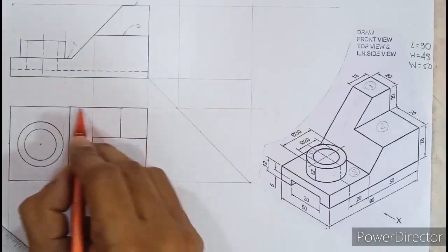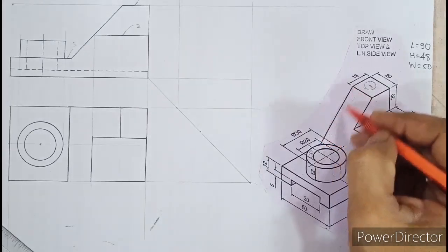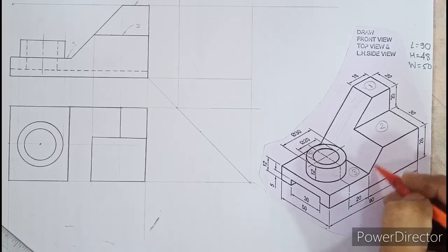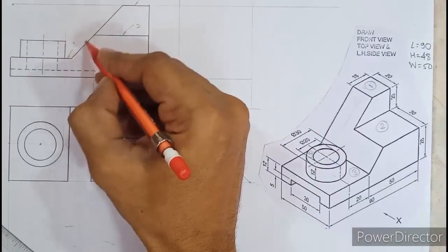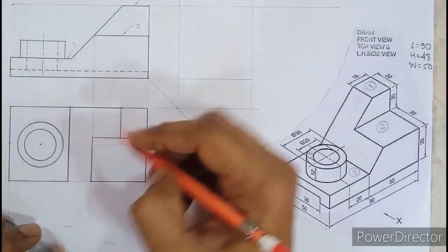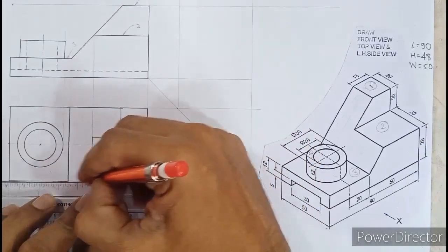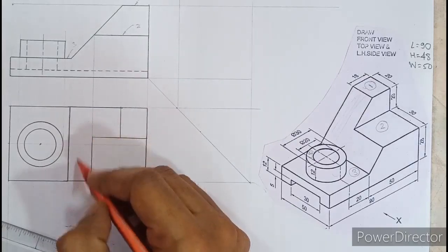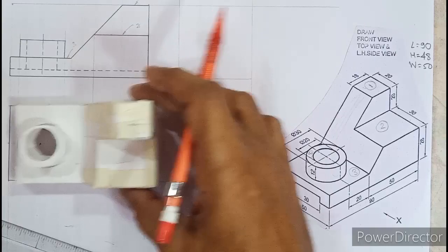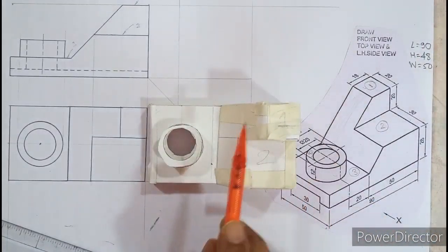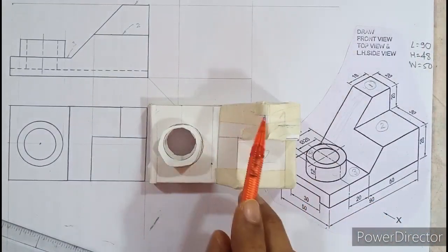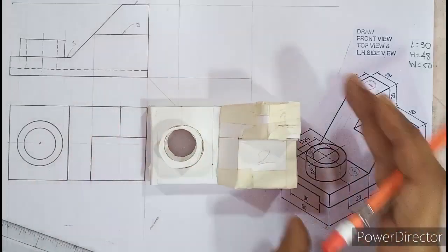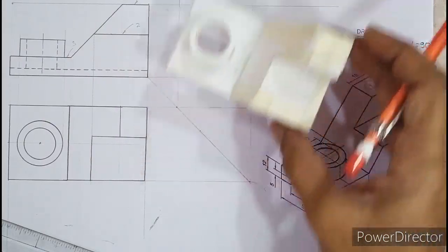see, this part represents the behind edge. Isn't it clearly visible? Similarly, if you look at this edge, it is a smaller edge and the lower one. So the smaller edge and the lower one, when you project both the lines down, you will find the missing edge over here. So when you connect them, this L shape is your apparent inclined surface. So see in the top view, what you can see is your apparent inclined surface. Same thing is over here, apparent inclined surface. So that is how top view we have completed.